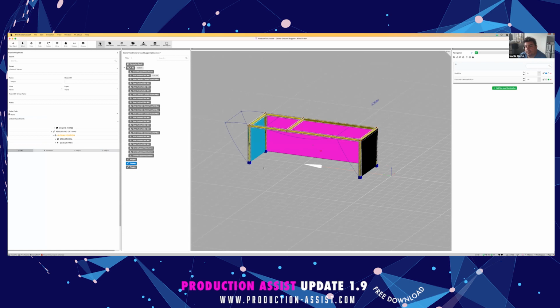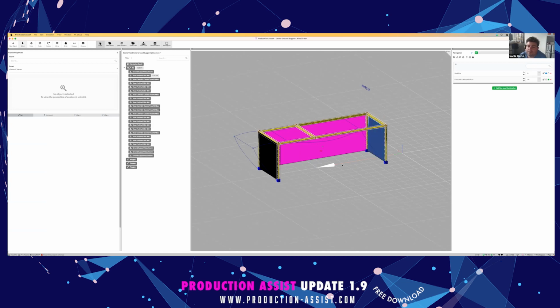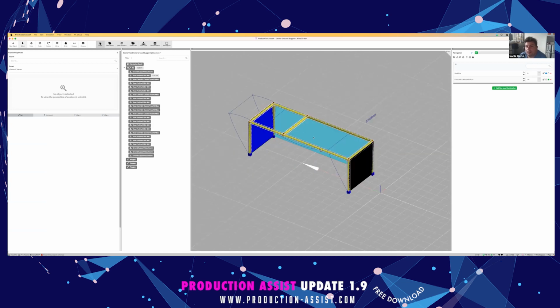These 2 planes, the light blue one and the dark blue one, actually take up this load. When the wind comes from this direction, the pink or magenta load plane does not really have any effect. So it's really mostly about these 2 planes.